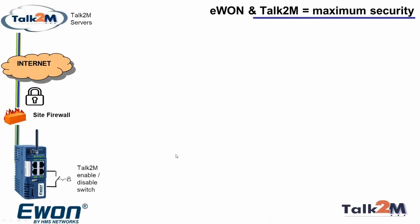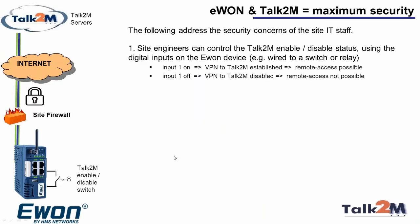Now, the very first thing is that you can enable an input switch to the Ewon. So on the back of the Ewon, there are a couple of digital inputs. And with those digital inputs, you can enable and disable the VPN, which was the green line we looked at in the last slide.